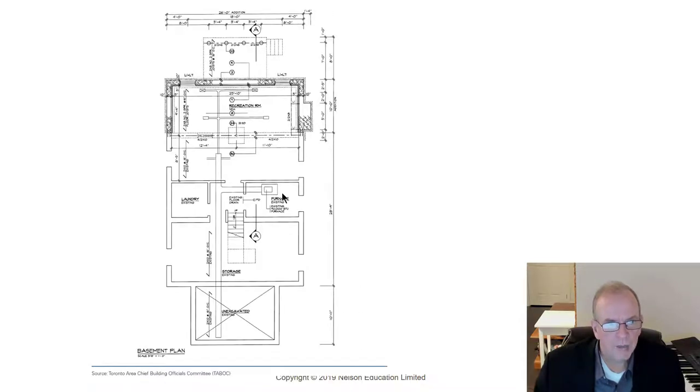And it is also showing you've got the furnace, which is heating the house, and it's going to heat this back area. Question is, you'd want to make sure that this furnace has the capacity for this addition, or in the specification somewhere there may be a listing to say to replace the furnace. Right here it's saying the existing furnace is 90,000 BTUs.